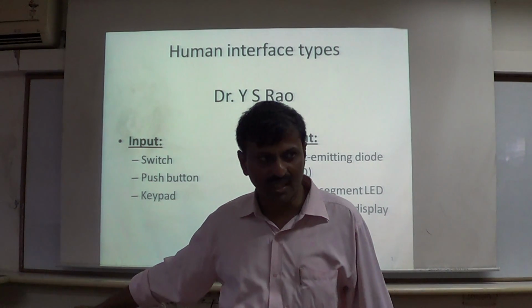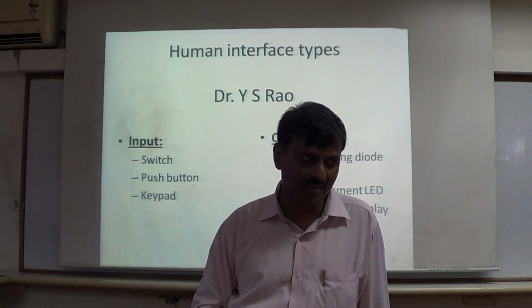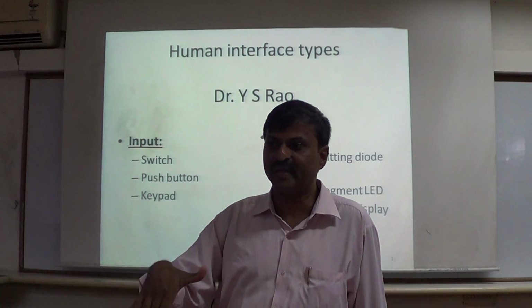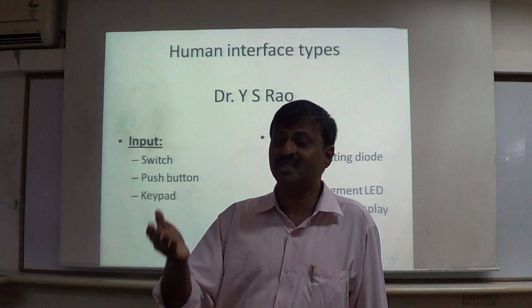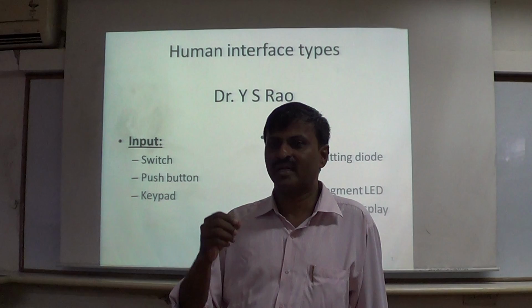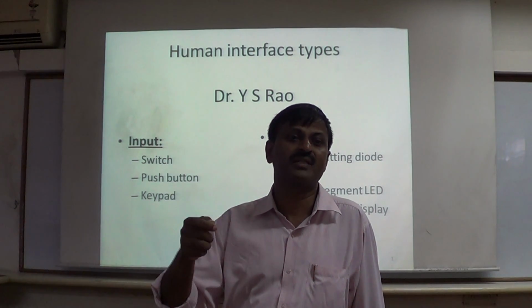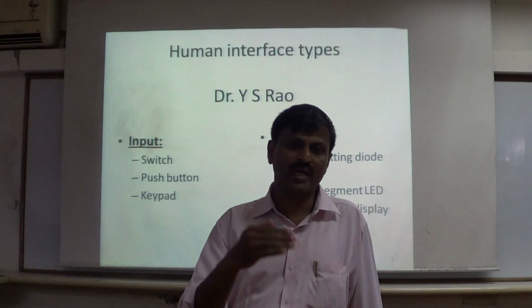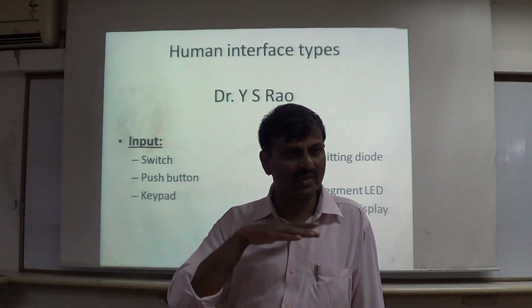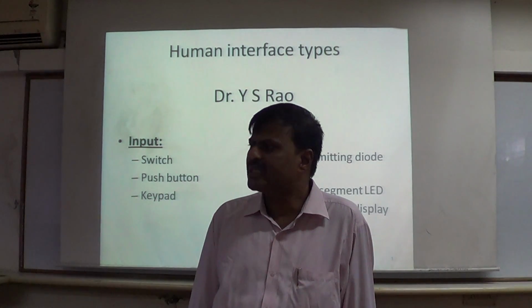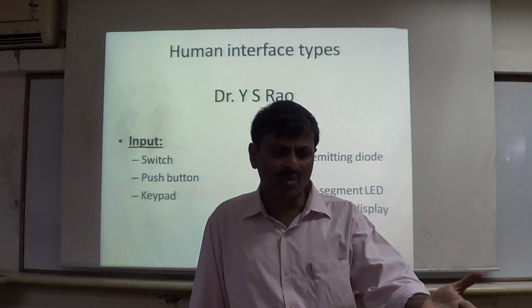There are 3 wires coming which are connected to the feedback control system. So it's not only a question of displacement, you will also have to measure how much displacement has actually happened, and if there is any error, that error has to again make the corrective action till the error is 0. And that keeps on happening, so that every 4 minutes there is 1 degree displacement as far as solar tracking is concerned.